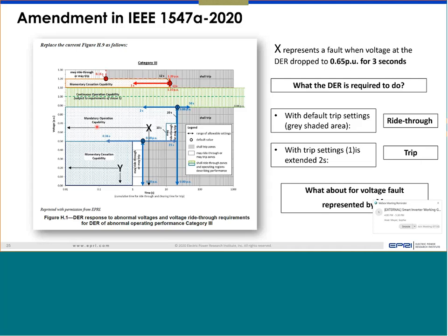I would say again the same thing. The warranties are typically 5 to 10 years, and may last even 15, 20 years with some parts replacement or periodic maintenance. So if you ask me, at this stage PV inverters have reached a little bit of maturity compared to some other new technologies like energy storage, which are still relatively new compared to PV. So you may experience more, maybe not catastrophic failure, but some troubleshooting needed for energy storage.